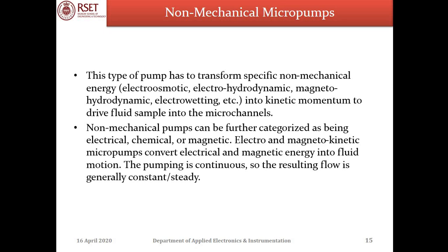Now this type of pump has to transform specific non-mechanical energy, as shown in the bracket. These are the mechanisms which we are going to discuss in today's presentation. They include electro-osmotic, electro-hydrodynamic, then electro-wetting, etc. So they are the mechanisms that are studied. What happens in a non-mechanical micropump is that non-mechanical energy is converted into a kinetic momentum so as to drive fluid sample into the microchannels.